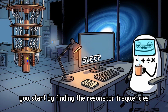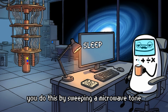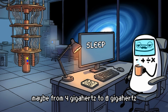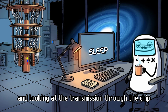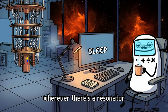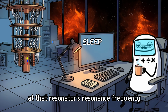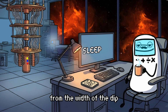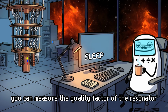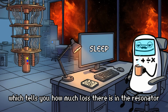You start by finding the resonator frequencies. You do this by sweeping a microwave tone across a range of frequencies, maybe from 4 GHz to 8 GHz, and looking at the transmission through the chip. Wherever there's a resonator, you'll see a dip in the transmission spectrum at that resonator's resonance frequency. From the width of the dip, you can measure the quality factor of the resonator, which tells you how much loss there is in the resonator.